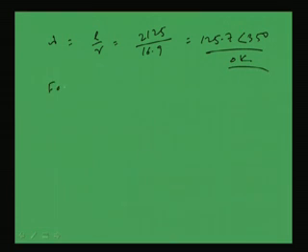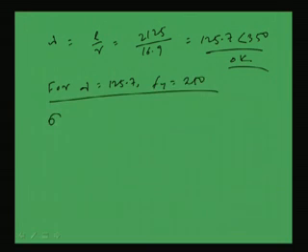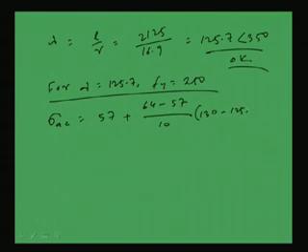Now, from table 5.1, for lambda equal to 125.7 and Fy equal to 250, we can find out the allowable compressive stress sigma AC, that will become 57 plus (64 minus 57) by 10 into (130 minus 125.7). From this I can find this as 60.01 MPa, right.